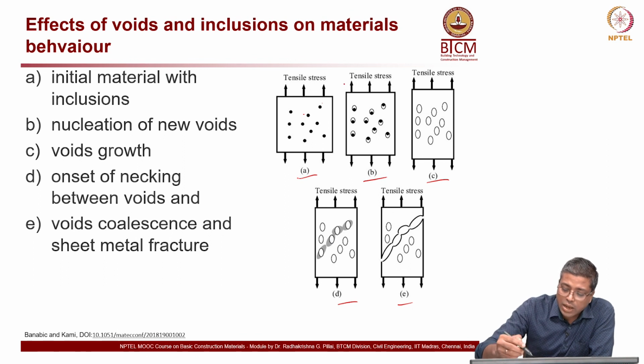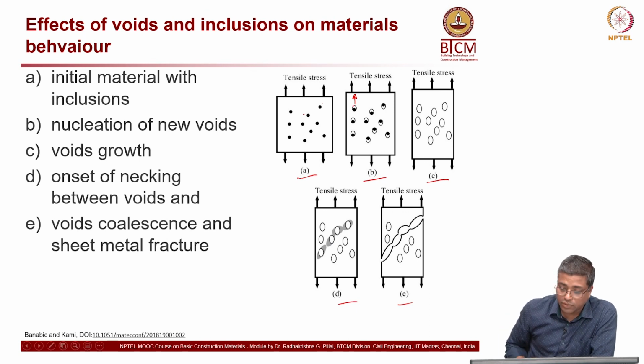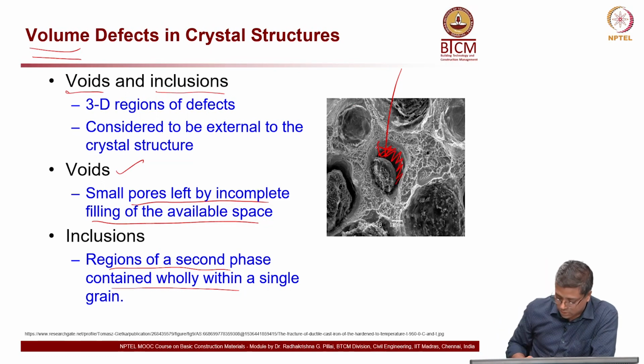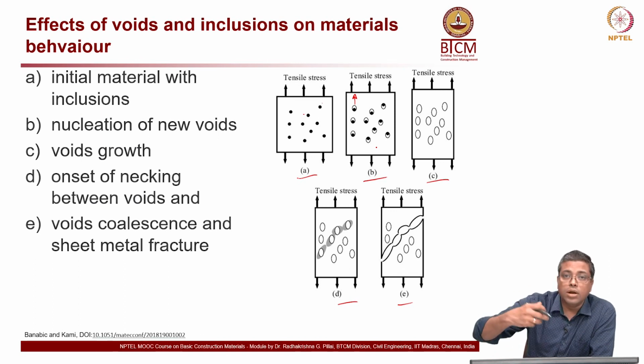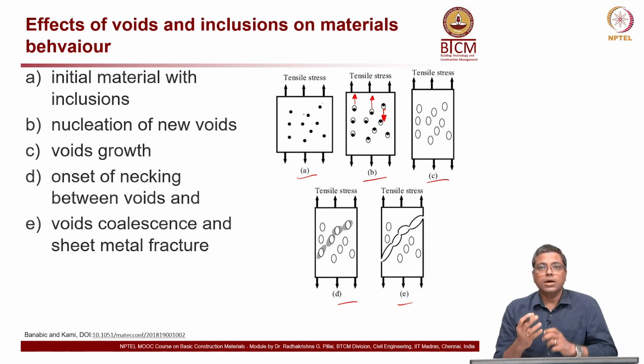As you apply this stress, what will happen is, you can see this particular portion getting elongated this way, and then the void inclusion is there. If you go back to the previous figure, you can see this space here. So as I pull, that inclusion gets detached, and then you have a stretching happening here. Here you can see it the other way, it is getting pulled this way. So, like that this deformation happens.